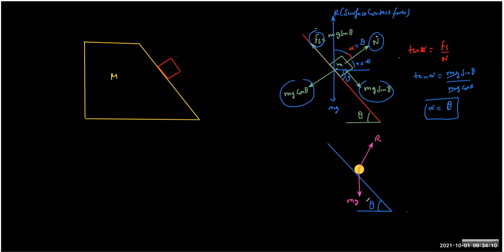I need not write all the other forces, and that is why I can resolve the forces into two components, Rx and Ry. We know that the block is going down with some acceleration a, which is known to us in advance. So now I can write Rx equals max, and mg minus Ry, because mg is dominating, of course, equals may. I'm taking the value ay downward.